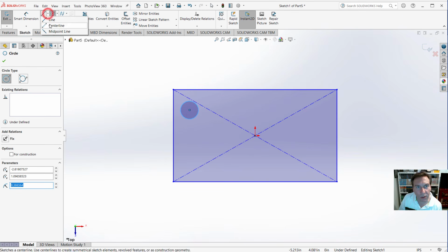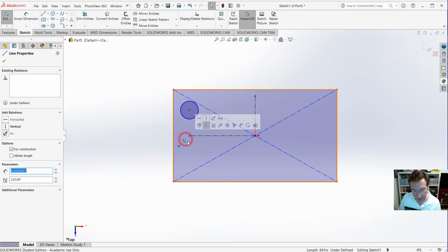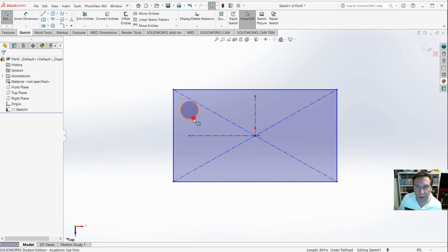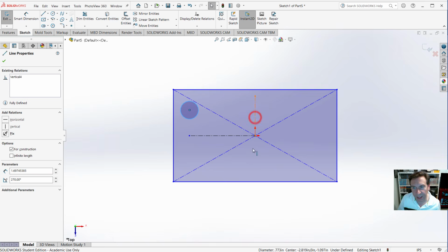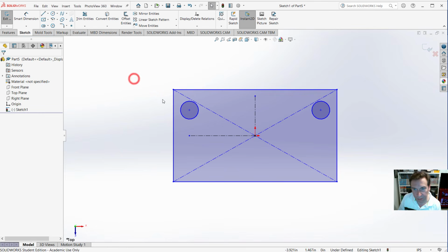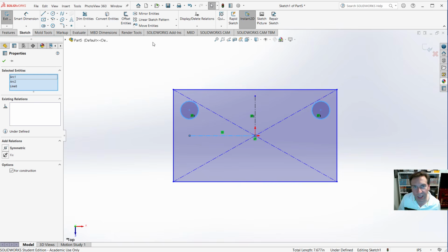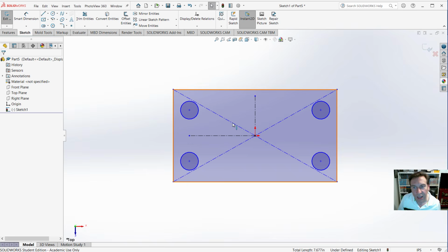I'm going to use the mirror tool. And remember, for the mirror tool, we need to have center lines. My keyboard worked. All right, now I'm just going to click that. Keyboard's working for a moment here, but still I'm just showing you some strategies. So we want to mirror that across. So we're going to mirror entities. Now we could click on these, get those 2 selected, hold Control, select that, mirror entities. I don't like to put the circle in right away because then you end up having to cut it twice. So I don't need to do it that way.